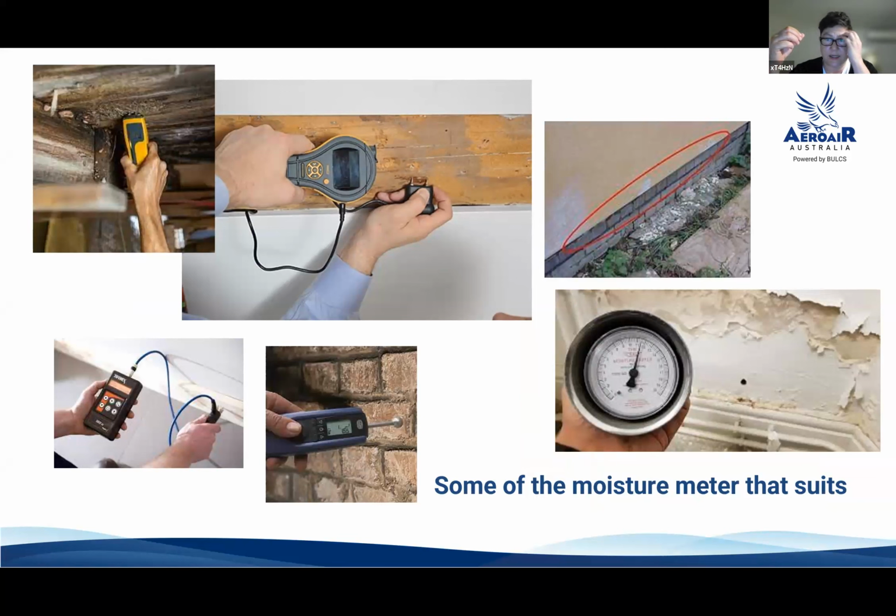And efflorescence are salt sediments on concrete that are pushed out, because all concrete has sediments in it. Sometimes when there is water logging, some of these materials will be pushed out through the water, because water is heavier than most other things, and it will just push them out. These white little films start to build on the surfaces, and those are what we call efflorescence.